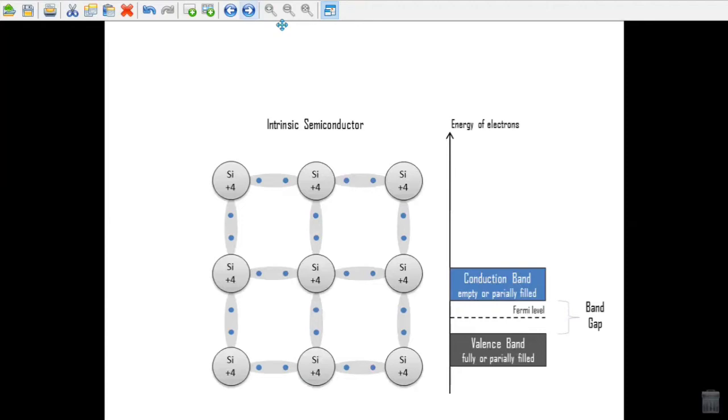Unlike bipolar junction transistors, it is a transistor with a region of donor material with two terminals called the source and the drain, and an adjoining region of acceptor material between called the gate. The voltage between the gate and the substrate controls the current flow between source and drain by depleting the donor region of its charge carriers to a greater or lesser extent.